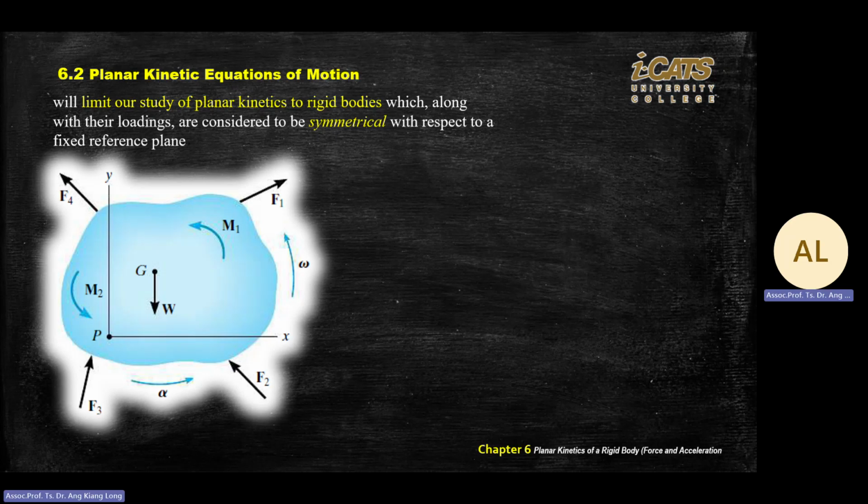So this object is having a weight, and all the weight is focused on the capital G point, and it's pointing down because of gravity. Right? And this object was rotating anti-clockwise. If you use your right hand rule, opposite is a positive value of your W. The W is positive, meaning coming up from the screen is positive because it agrees with your right hand rule. And all the small F1, F2, F3, F4, they are external forces. So these are all vectors, and you can split them into X direction and Y direction.